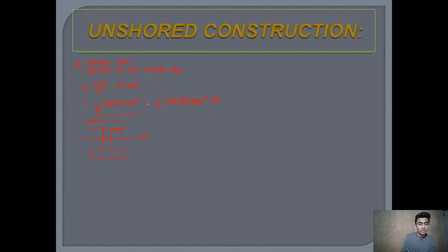And since I considered the whole diagram and our section is an I section, I will have to subtract this part. Now these parts are equal, which is why I multiplied it by 2. And no need to add AD squared because their centroid rests as well at the neutral axis. So the value of I is equal to 1 all over 12, multiply that by 225 times 375, raise this to 3.